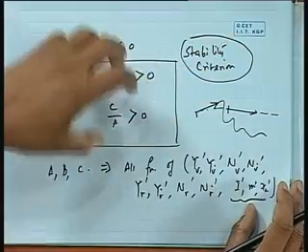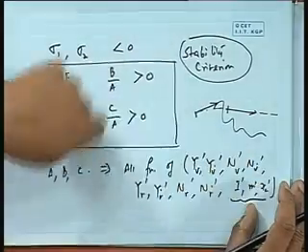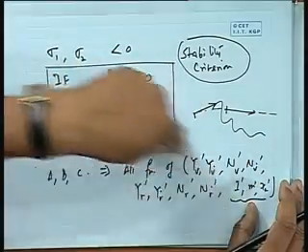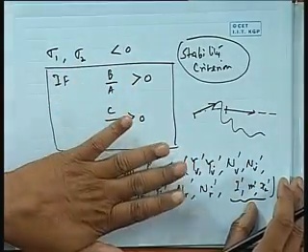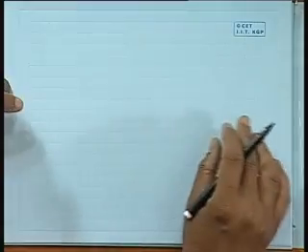So, we have to relate this condition with those parameters, and let us now look back at these parameters a little more deeply, because this is what is called hydrodynamic derivatives. Then I will come back, because we have to relate stability criteria with the derivatives. If you can find the derivatives, then you can tell that this ship has this derivative and satisfies this, so the ship is going to be stable. Just like when Gm is positive, the ship is stable.